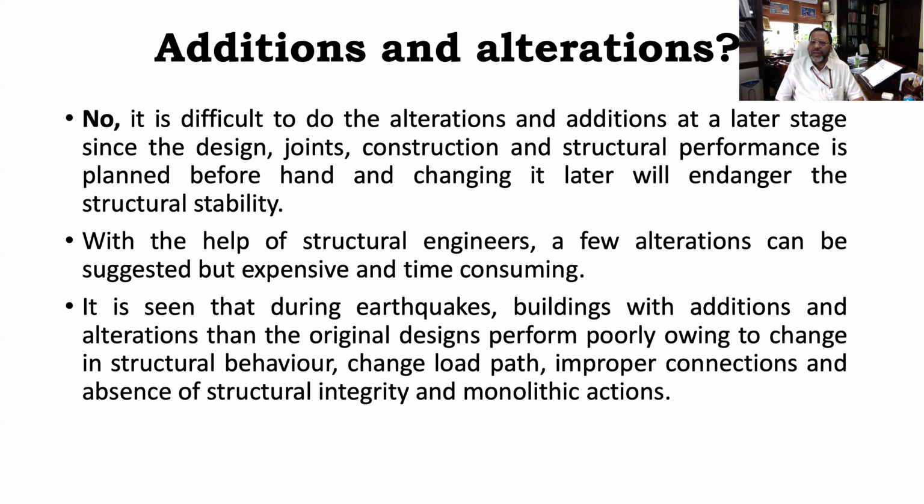And also we have seen alterations and additions being done without applying engineering judgment and without seeking help of the experts or retrofitting experts. They normally perform poorly during future earthquakes, because by doing those alterations or additions, we change the structural behavior, we change the load transfer path, and the structural integrity in monolithic action is compromised.